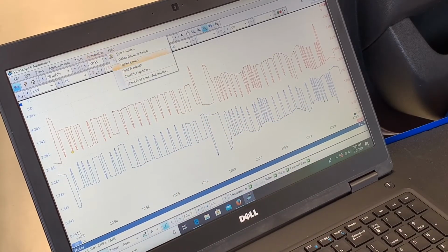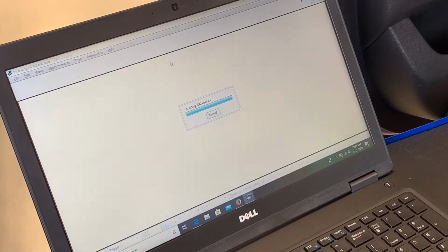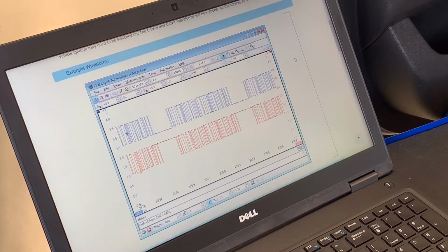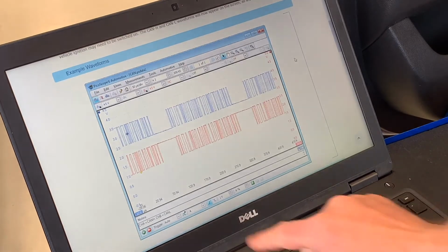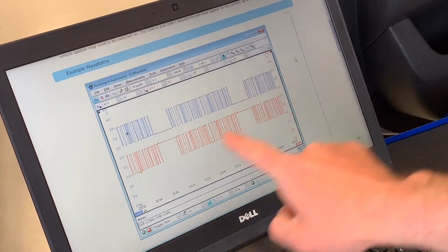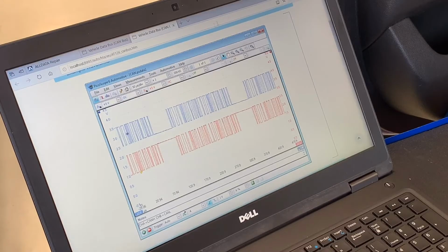If we go pull the example waveform that PicoScope has, that'll save us some time from chasing our connection issue here. This is a better example of what we expect to see, and really what I think is occurring on this truck. I'm just having a poor time getting the connections without noise and interference. So here you can see really sharp on-offs, very consistent voltage values at the top and the bottom. That's critical and that's important. And if I was looking at this from a diagnostic end, that's really what I'd be looking for.